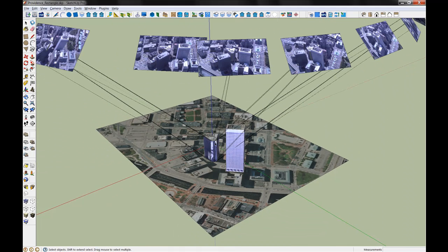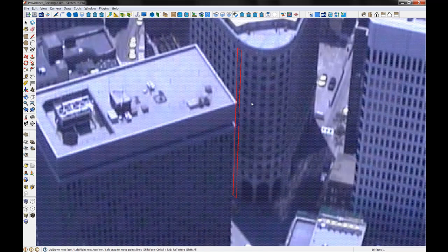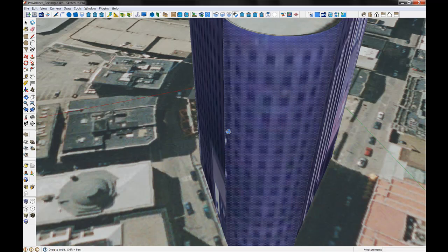Because of the curvature of the angle between the facets, they were textured from different aux views, but we can override that using the TextureFace tool. We can see that whole curved surface in this aux view, so we'll select that, and now when we say to texture that, we can take all the faces, adjust them, and then apply them so that we have a smooth texture across that curved surface.